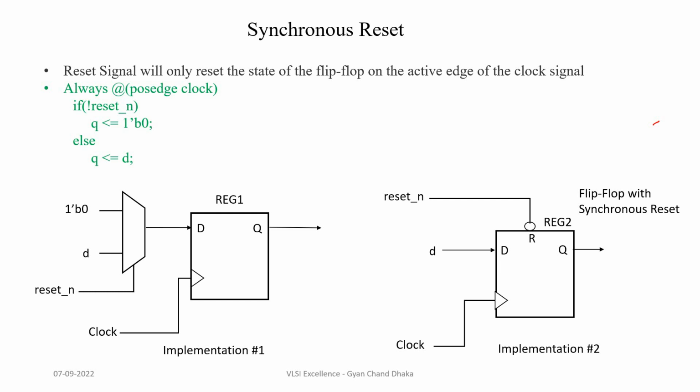And finally, we will see which is the best reset design technique for our design. So let's get started. First, we are going to cover the synchronous reset mechanism. As you can see by the name, in synchronous reset, the state of the flip-flop can only change on the active edge of the clock signal. In other words, the reset signal can only affect the state of the flip-flop at the active edge of the clock signal.